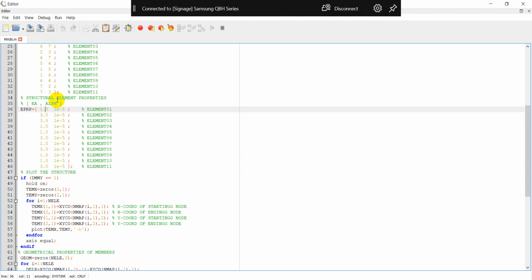If you go with megapascal, the force unit has to address that mega also. So better just clear out the kilo, mega, or milli. Just bring it back to Newton and meter. Don't keep the centi or milli over there.